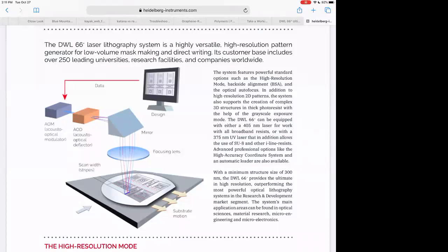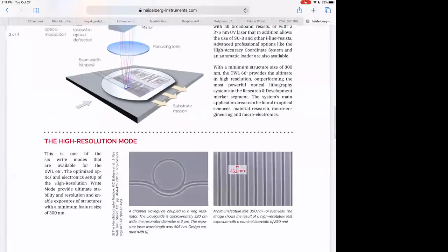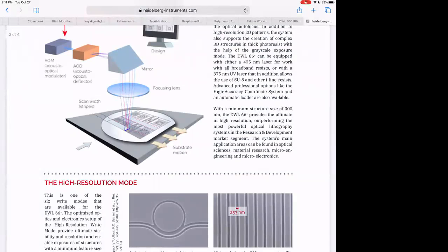And so this DWL instrument is not stereolithography, it's just lithography. So that's 2D on a wafer versus a real 3-dimensional system where you have differential layers, because there's nothing in the DWL that can make the next layer, right? There's no stepping of the Z height in this instrument, this is only stepping around in 2 dimensions on a wafer.